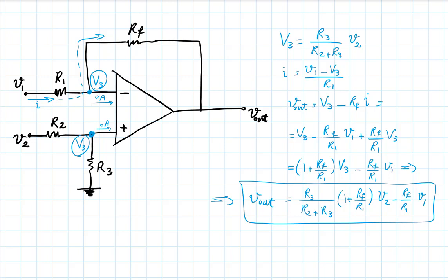Now, if you add things up, what will you get? You will get the equivalent of R2 being 0. Go see if that works out. Notice all these things that I'm doing now are just solving a circuit. The only piece of information that you know that's new here is that there's this device that doesn't take input current and would like to make sure the two inputs are at the same voltage because of the circuit. But the rest of the solution is just your basic circuit solution.